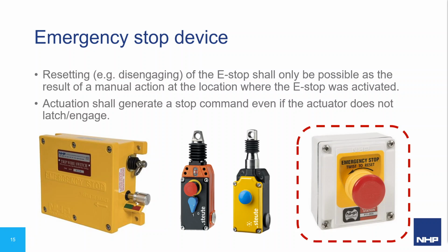This is one of the reasons why we have a separate manual reset button in the safety control system, which ensures that if the emergency stop command is given, the machine cannot be restarted until everything has been acknowledged and reset.